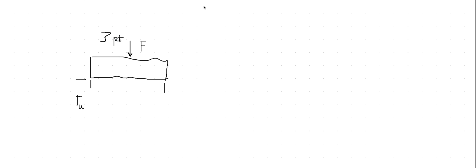Now, if you have a 3D version of that, because the specimen is really not 2D but 3D, you have something like a box. Then you can generalize this, so you recover these 3 supports. Then you have to remove something so that you cannot rotate around one axis.